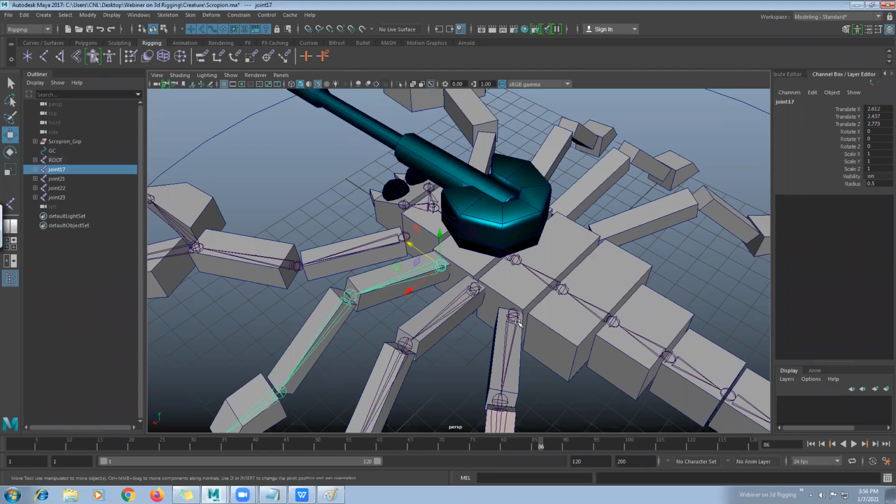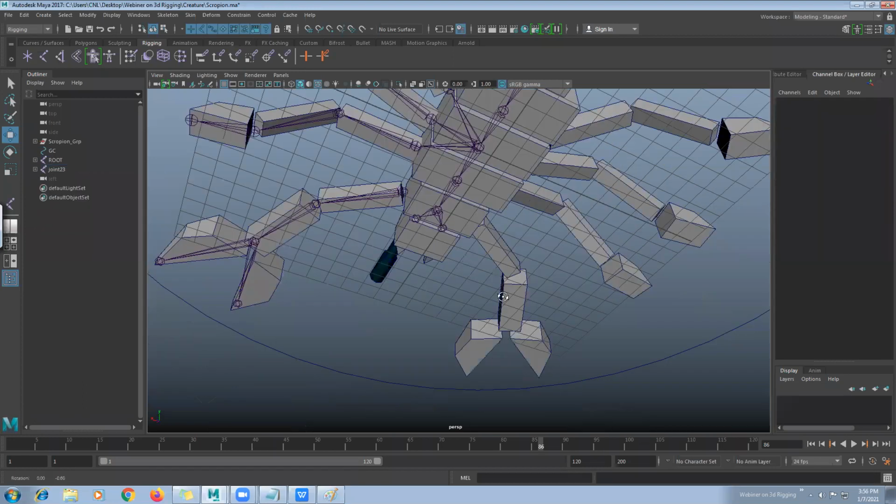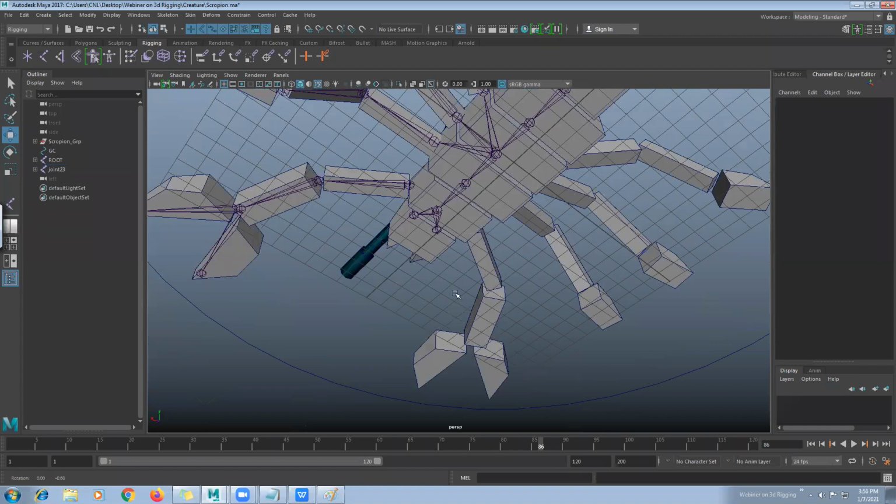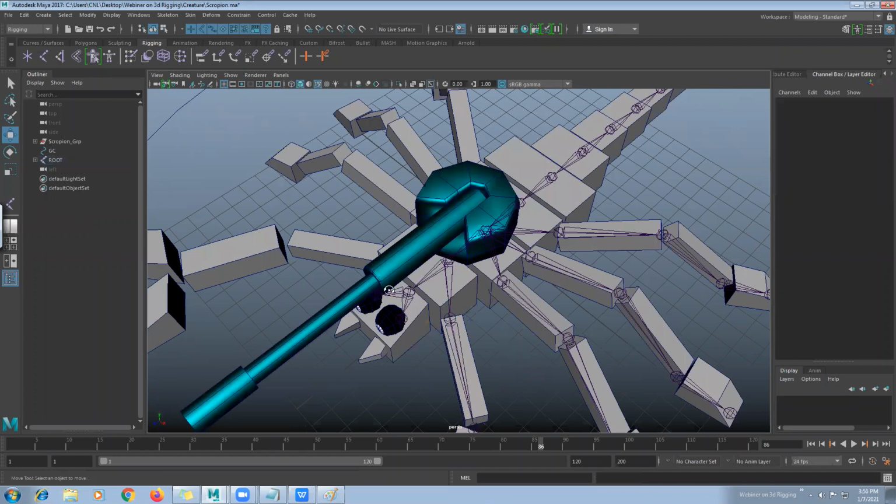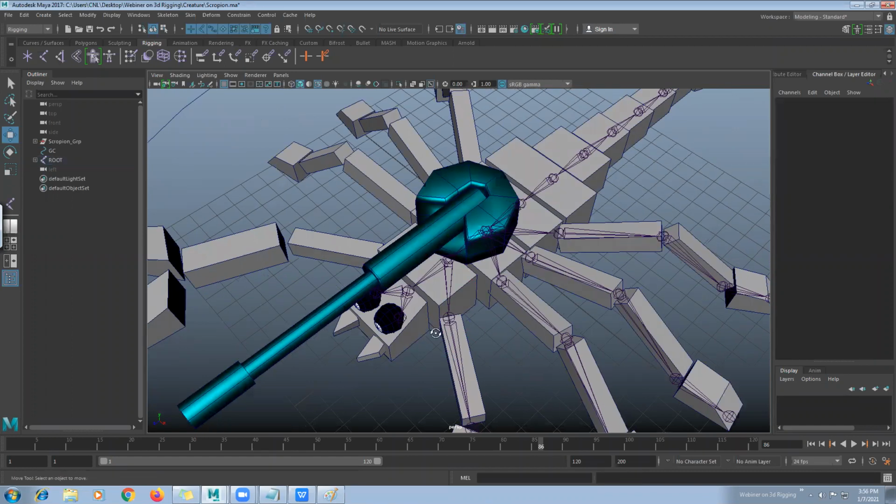For example, if I select these 1, 2, 3 and target this bone, then hit P. That means all the joints should be connected to a single piece of bone, and this is the armature or hand of it, so we should connect it with a separate bone. Those are two different assets. So it's very easy to do that.